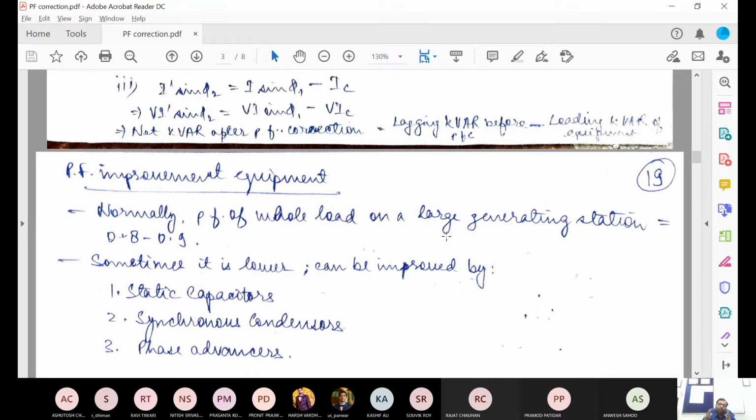Because if you recall, there was this phasor diagram which we drew earlier, with V, phi, EA and the current. If you change the magnetic flux in the machine, then EA changes and accordingly the current and voltage adjust, and not just the magnitude of the voltage but also the power factor changes. So the thing of interest for adjusting the power factor would be the excitation system and the excitation control.